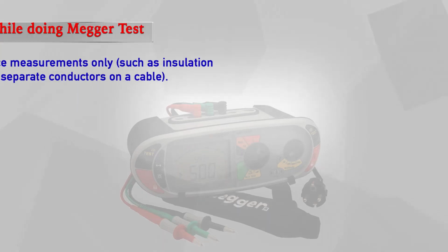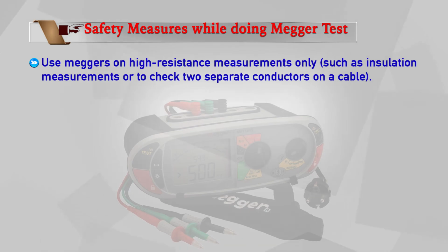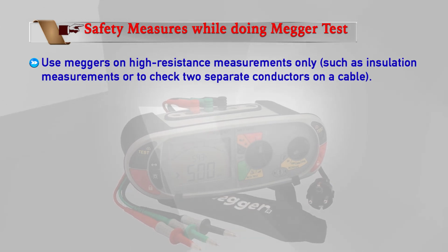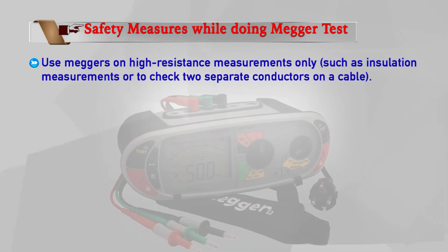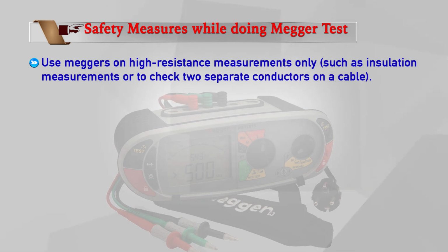Now what safety measures should be taken while using the measure? When the measure is used for testing purposes, injury or damage to equipment can occur if the following minimum safety precautions are not observed. So what do you have to do? Use the measure on high resistance measurement only, such as insulation measurement, or to check two separate conductors on a cable.